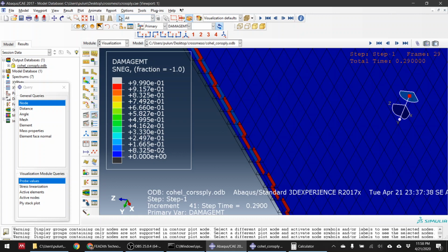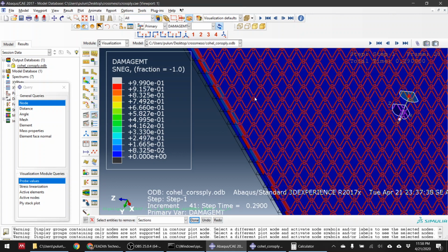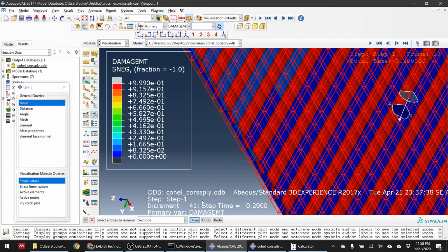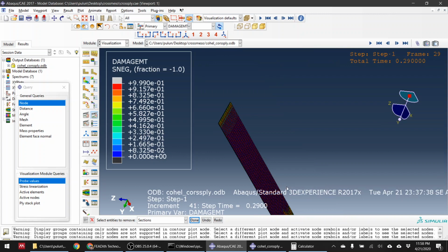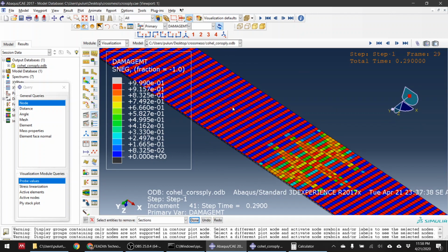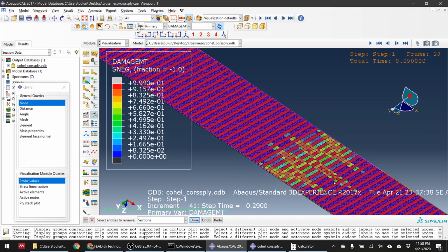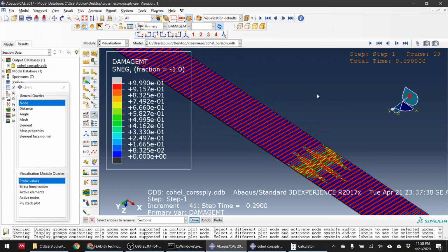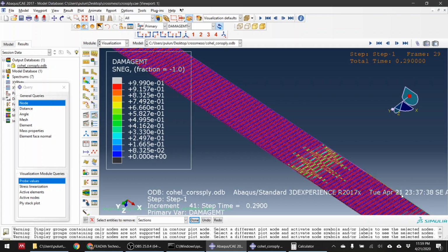I want to show you again. Wait, remove selected here. Done. So here, yeah, damage happens everywhere. There's many transverse cracks. Yeah, it makes sense now. Something like this happens because we are exceeding the strain that is required to initiate the transverse crack, and now all this region has the same threshold of transverse cracking, that is 40 MPa.